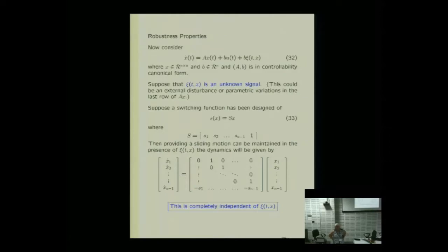It is not important. It is only the magnitude that is important. It would have been the same if it wasn't a sinusoid. If it was some other signal that was no bigger than plus or minus 1, we would have got the same performance. It goes without saying that it should be bounded, because clearly nobody can deal with unbounded uncertainty, because if you have unbounded uncertainty, technically you need unbounded control, and so, you know, things fall down. So it definitely needs to be bounded, but it is purely down to knowledge of the bound, if you like. The transient or dynamic characteristic of the signal is not important. It's only the bound.